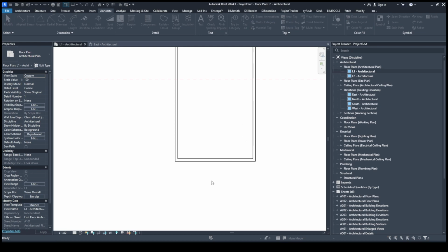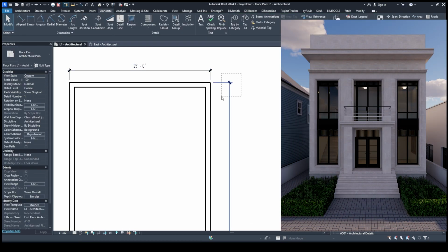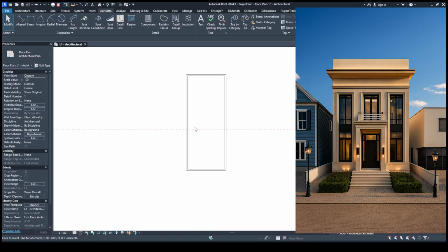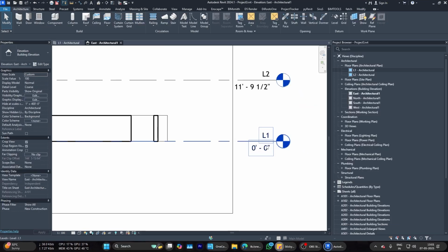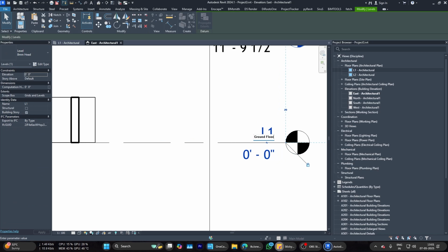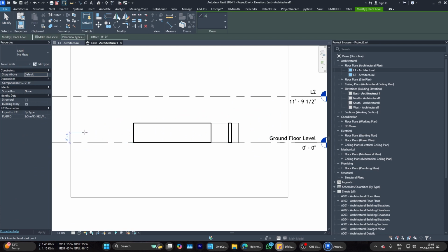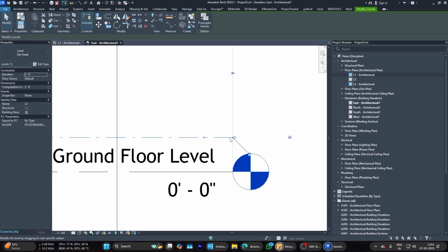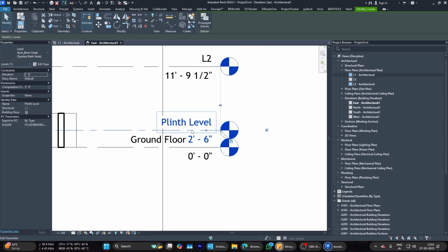In today's video, we are going to make a neoclassical house architectural design with a photorealistic render with the help of AI models. Remember, in Revit, the first step is to set the levels for the floors and set the height as per your design or standard heights. I'm just giving a value to the floors, and you can check here the ground floor, the plinth floor, the first floor, and the roof floor.